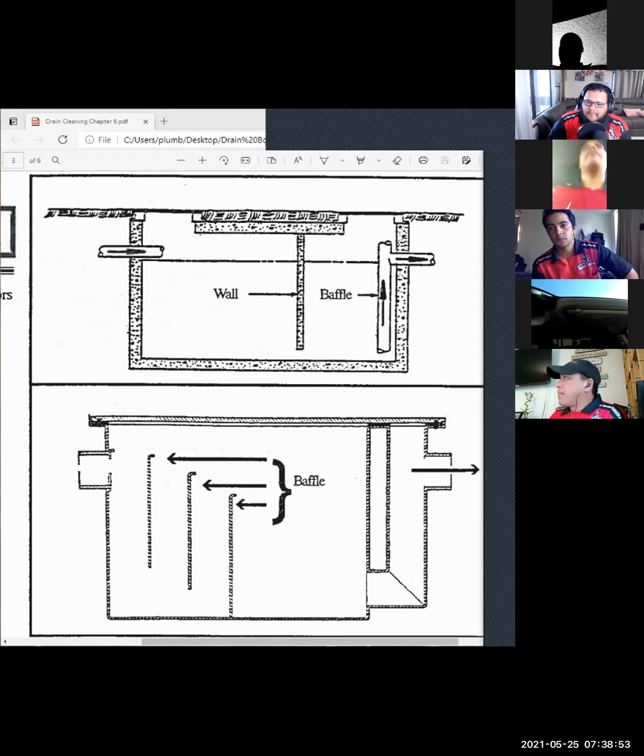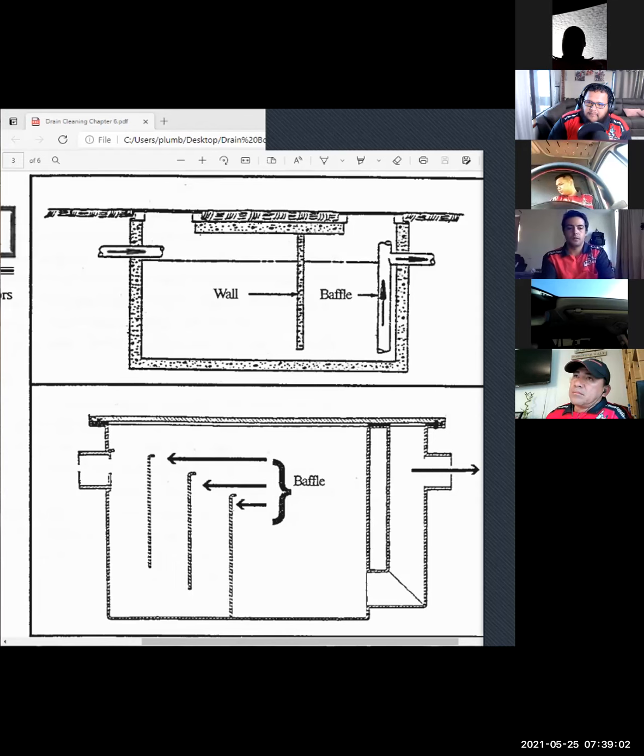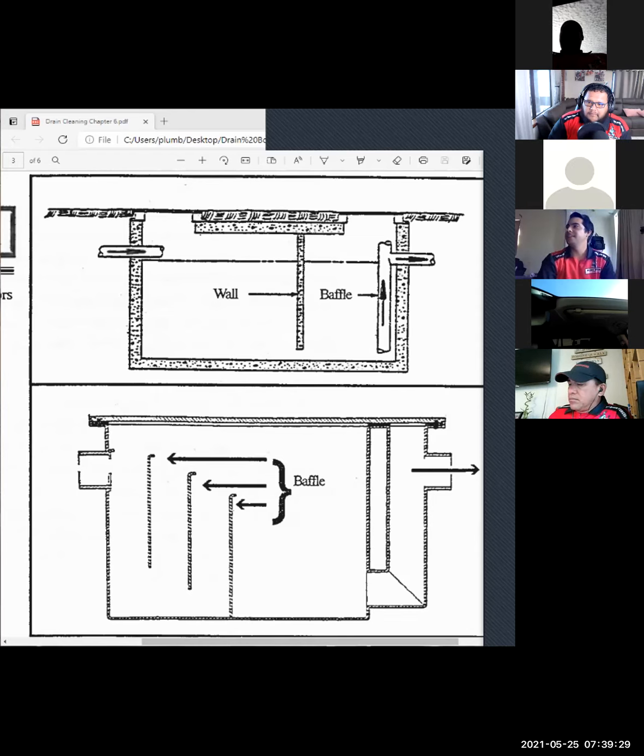So a plumber or the purchaser of the grease trap system or the waste system for a kitchen has to pay for a plumber to run a separate line from those hand wash sinks all the way to the waste system, which is just another piece of ignorance. But when it comes to calculations, it doesn't change a thing. So I don't believe that you would get in trouble for running a hand wash sink to it in order to eliminate a bunch of piping. We're only doing a little bit of that work. We just did that kitchen in Lahaina a little bit ago, but most of the time you guys aren't tearing kitchens out and putting new waste lines in. But when it comes to the grease trap, it's pretty simple. Anything that can collect grease needs to go to the grease trap.